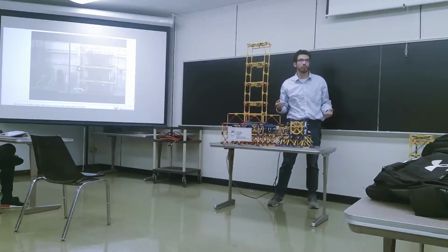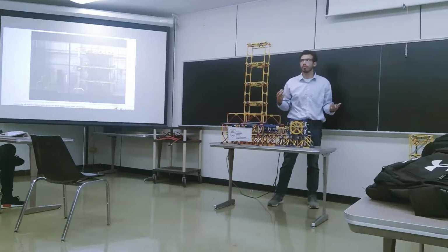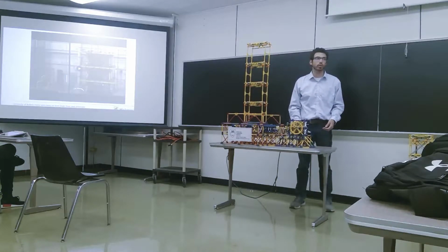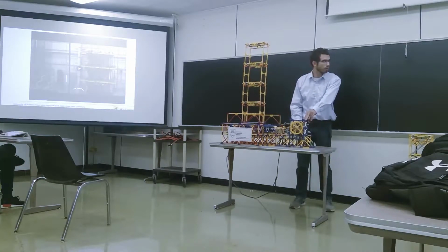With no mass in the system, if you have an acceleration excitation, there will be very little effect seen by the structure. The mass is what causes the force. The more mass you have, the more force you have. So I'll just get it going and show some forced vibration and see how it resonates. Can you even see it? If you want, you can come closer to it.